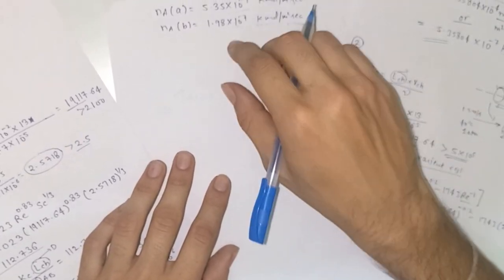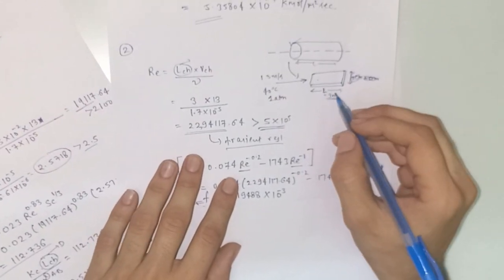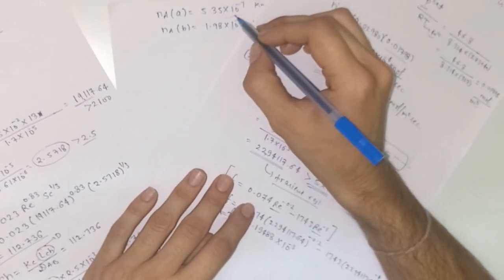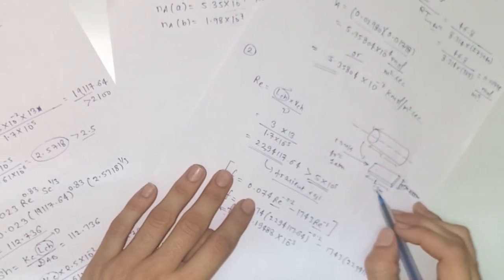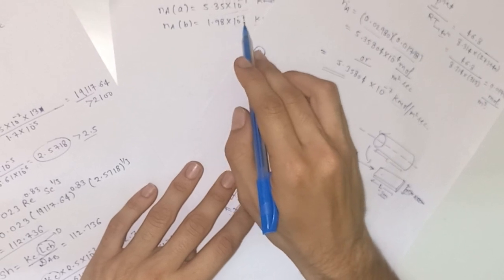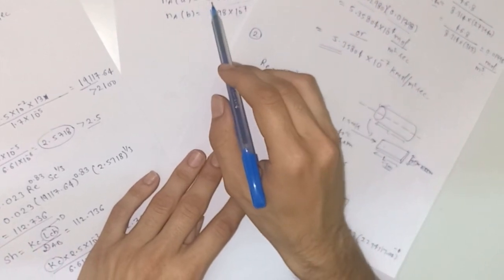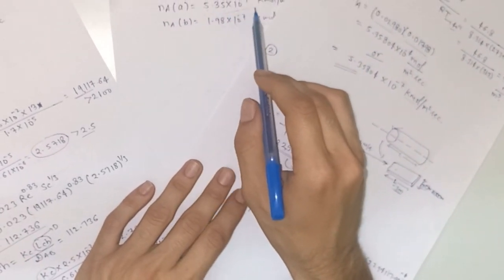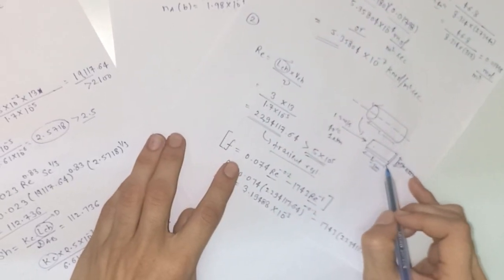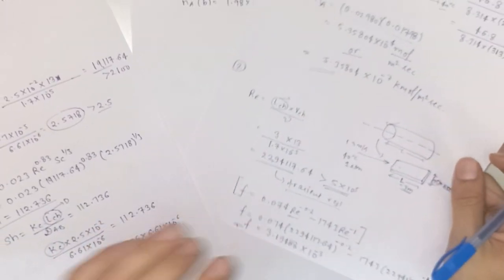Now in the third part we need to calculate the length of this flat plate such that the flux is equal to the flux we calculated in the first part. Because we know that the length is 3 meters, we got the flux as 1.98 × 10 to the power minus 7. So for the flux of 5.35 × 10 to the power minus 7 kilomoles per meter square per second, what should be the length of the flat plate so that we get this as the answer for our flux? Now proceeding with this question,